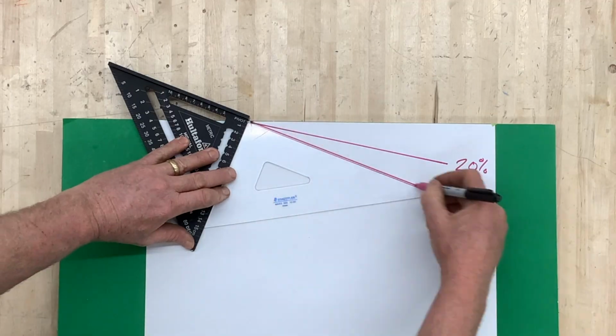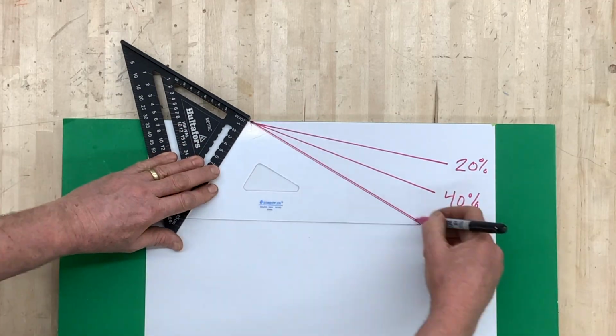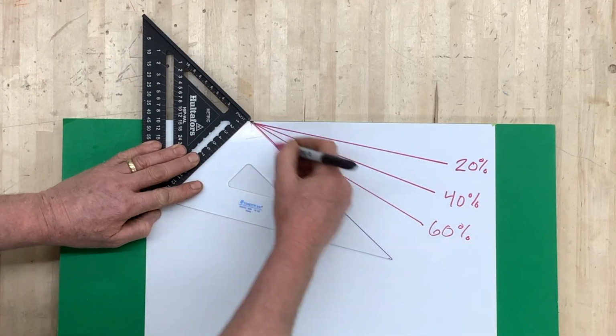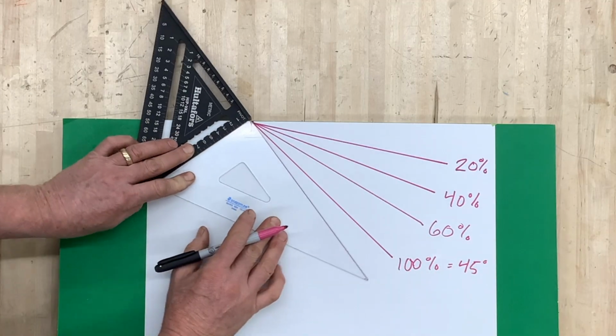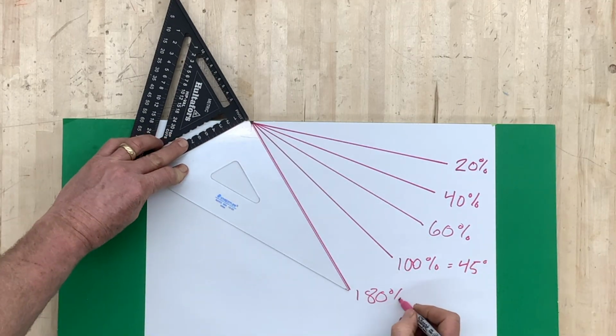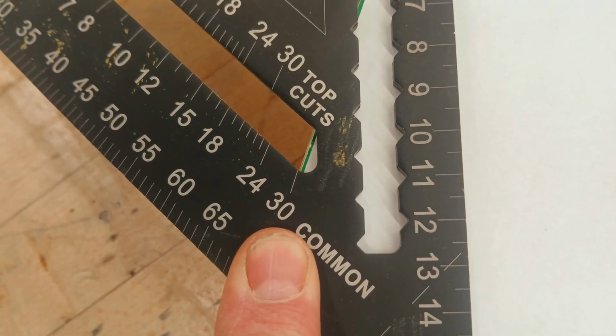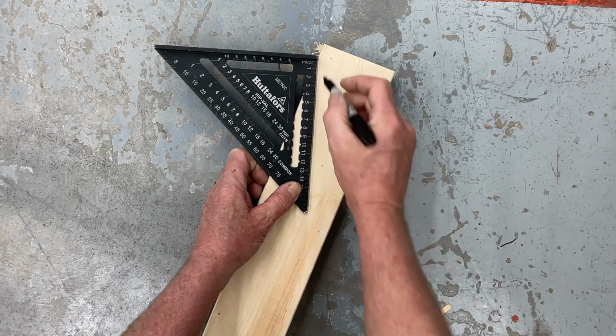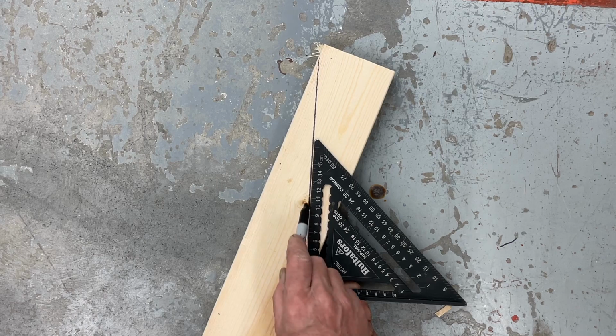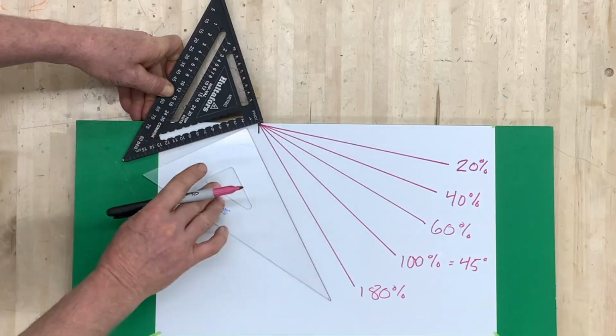Percent slopes are interchangeable with the decimal slopes used in some countries, including Japan, which use units of rise per 10 units of run. Aligning the number 30 on this rafter square will give a plumb cut for a rafter with a 30 to 10 slope, which is the same as 300%.